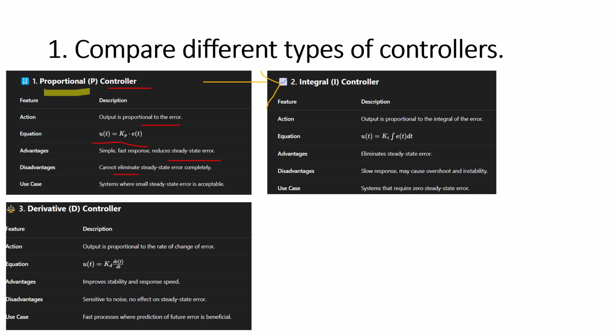Okay, so the same thing, in the integral controller the output is an integral of the error, and for removing the proportional sign we put Ki here, which is the integral coefficient. But the problem is that proportional control is fast and simple, while integral is slow and may cause overshoot. So the same thing with derivative control: the problem which we had is overshoot and instability.